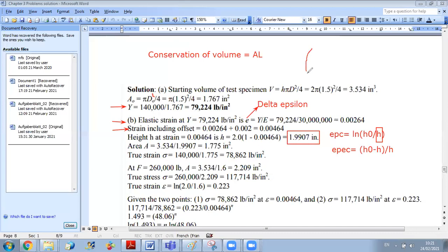The final shape will be like this if you want, okay? Because at the end, you have resistance to increase in cross-sectional area. But as you go to the center, it will be more uniform. But since they said here to neglect this effect, we can assume that the volume can be calculated as cross-sectional area times the length. And we assume uniform cross-sectional area over this pattern.